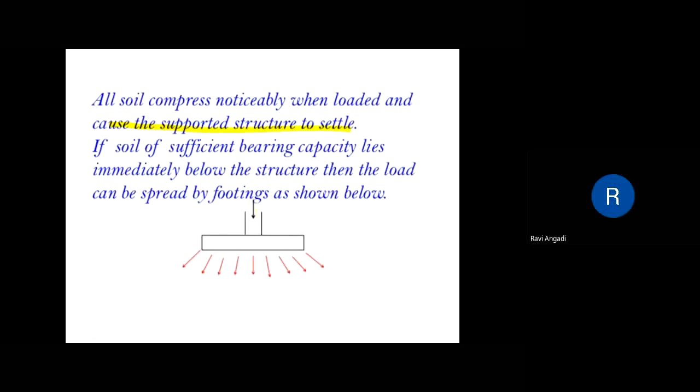So whenever this load is applied, it will compress the soil down, and the supported structure may settle. If the soil lying immediately below the structure has sufficient bearing capacity, then the load can be spread by the footing as shown in the figure.